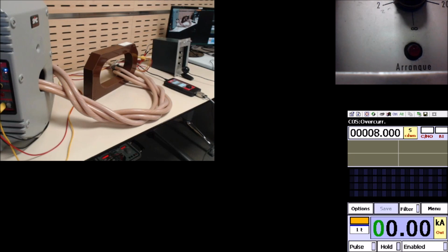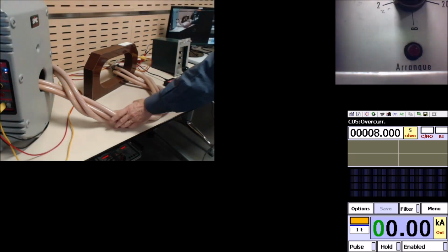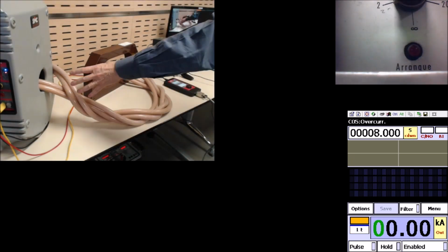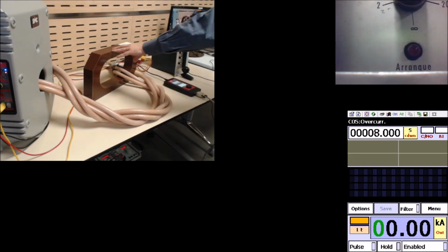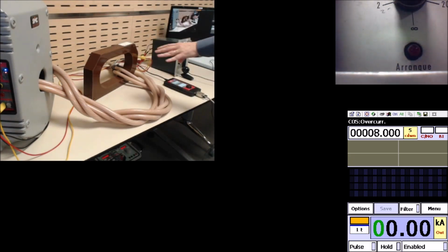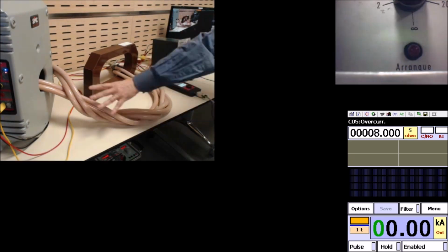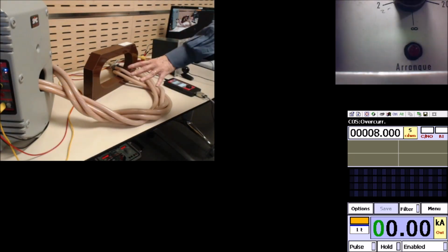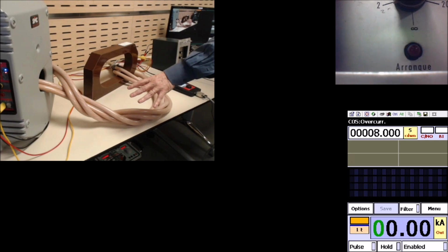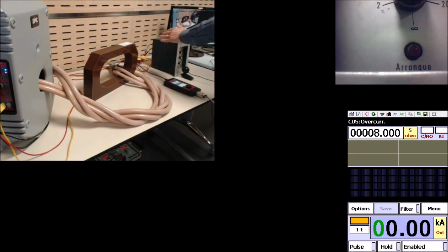What you can see is the relay that we are going to test here. Okay, the Raptor system, the high current output from the Raptor, and a current transformer here. So the current transformer will be used to downsize the test current. Using this output in the Raptor, we will be using thousands of amperes. So in order to test the relay, we need to downsize the current using this transformer. Okay, downstep the current to secondary values.